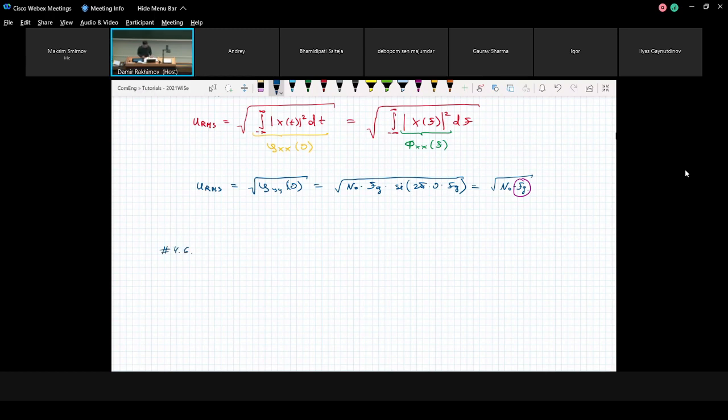Have other questions. So we have the following impulse response, g of t equals S of t times 1 over T, exponential of minus t over capital T. If I plot this impulse response, it goes from 0 to plus infinity.